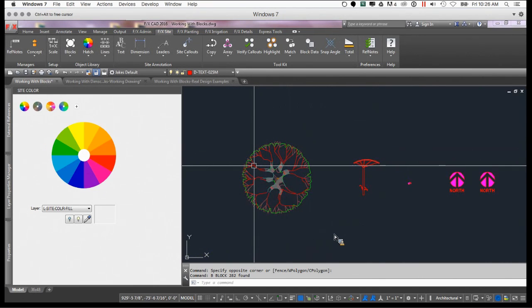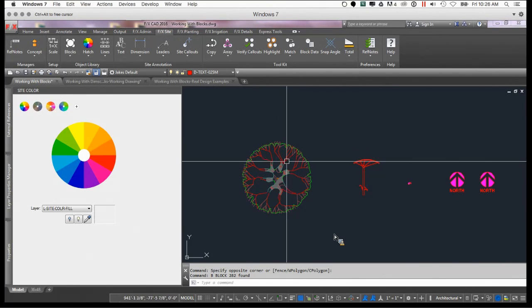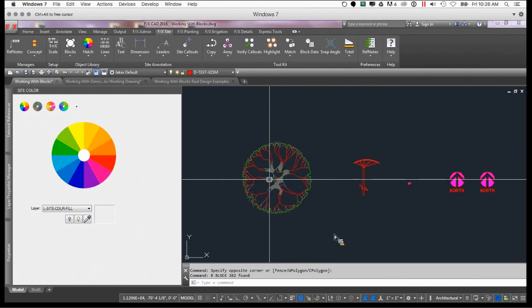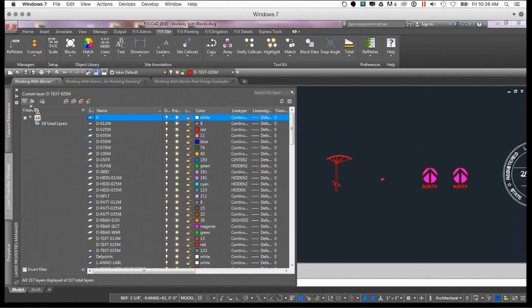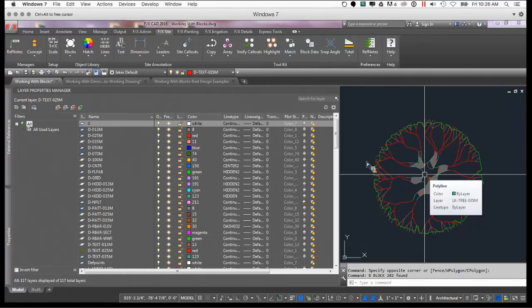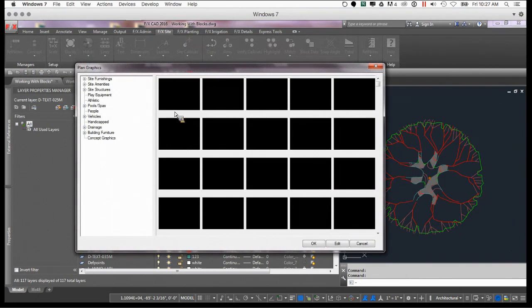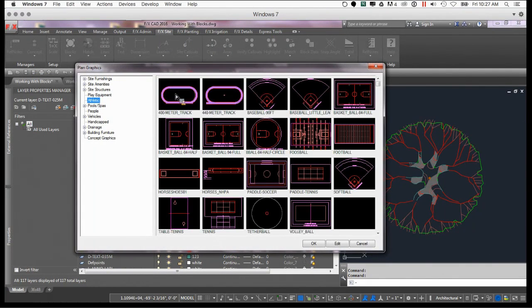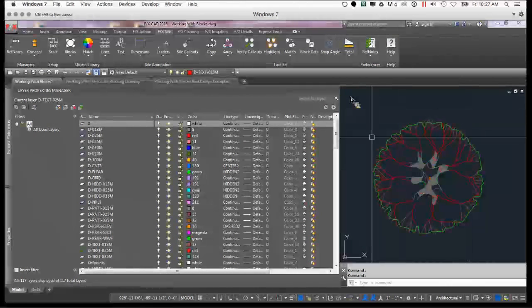to save this guy into Land Effects, because once you do save this in, you do need to see how it looks so that you can choose it. So basically a preview slide. So what I want to do is I'm going to get rid of my color guy here, and we're going to shrink up the frame here. And basically, if you've read any of our documentation on how you save your blocks in, you know that we save or snap a slide that displays here. So as you look at one of these, these are all slides that AutoCAD is letting you preview so that you know what to pick. So we want to make sure that that slide looks really nice and it matches roughly that aspect ratio of that item.